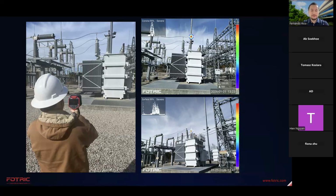Tracking, for the ones that are not familiar with the term, is basically when electrical charges start, let's say, leaking or finding a path on the surface of the insulator. The higher the voltage, the higher the likelihood of this occurring. And these charges, more known as partial discharge, start breaking down the insulating properties of the insulator, causing at some point a full discharge to occur and find ground through the body of the transformer.